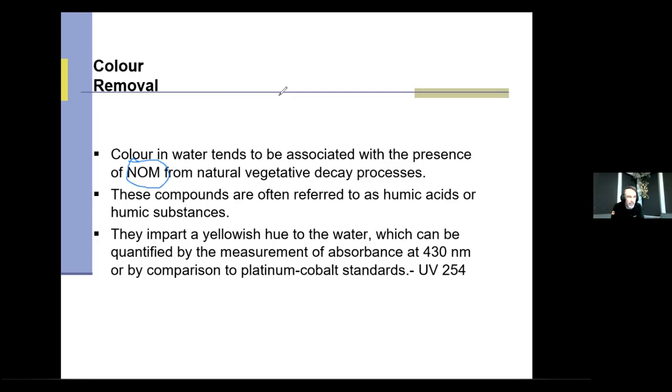And again, it's compared when we check it in the lab for color. That color we look at through the absorbance at 230 nanometers, or a UV254. And these are devices that measure color. And again, when I have color in my water, it equals organics. So more color, more organics. We need to remove this color.